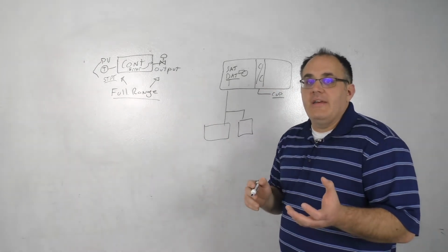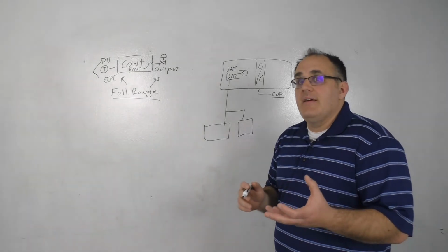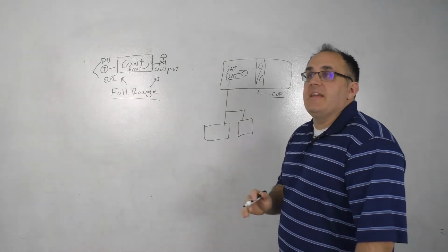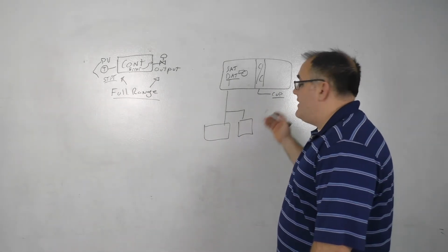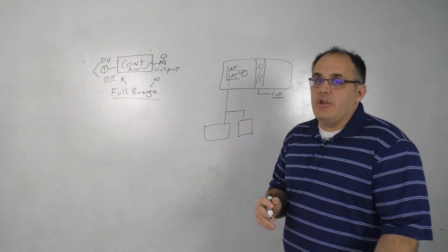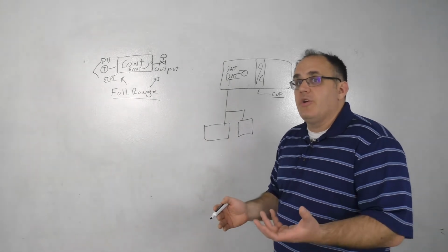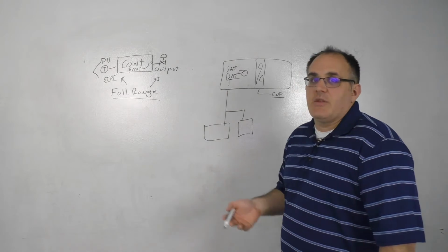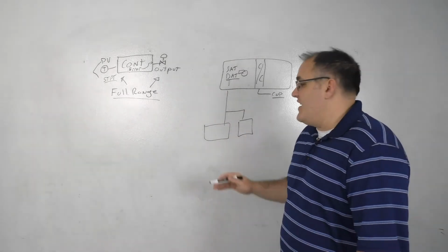When the coil is less likely to open, that means there's less pump energy required. That means the cooling to provide to that secondary loop or primary loop is lowered, so it has upstream effects as well as just reducing the wear and tear on the equipment of the air handler.